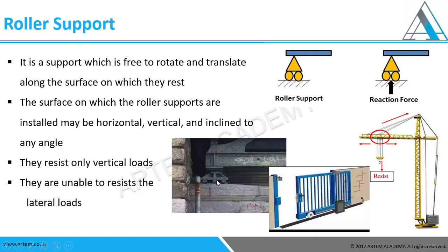In bridges, you might observe this whenever you are traveling on or next to them. It allows the bridge to expand or contract based on temperature changes, where there is a slight variation in the length in the steel properties. That's why on all bridges, one side is fixed with a hinge and the other side is allowed to move for lateral forces. That's why they make it a roller. Day to day, according to the application or functionality, how the constraints or supports change.